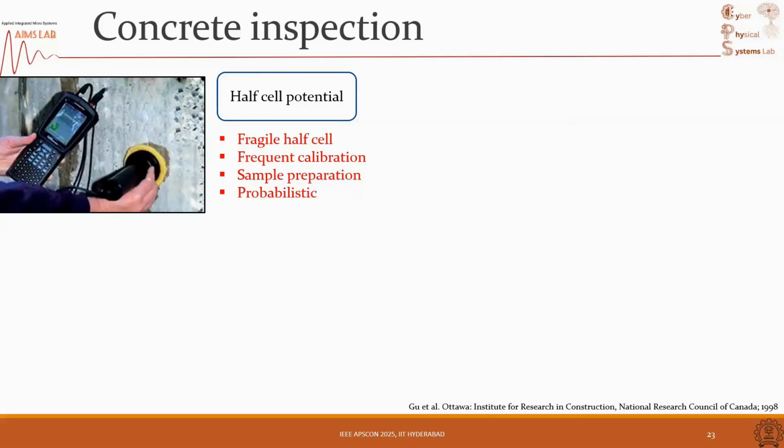So inside concrete, you have the steel reinforcement. So you have to remove some of the concrete cover and connect one electrode. So this is also an electrochemical measurement. You connect one electrode to the reinforcement and one electrode on the concrete. And then you do an open circuit potential measurement. That's all that it is. But you need a potentiostat here as well.